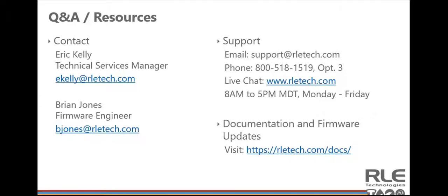That is correct. A lot of times what we'll find is the power will be somewhat variable. I see this less in data centers when the units are connected to a larger UPS that's doing power cleaning and whatnot. But that's essentially what's happening. The small UPS that your system is connected to is making sure any of the power fluctuation, brownouts, low voltages are not hitting the controller. And that can cause a little bit of jumping around in footage or some odd behavior from time to time when it's getting quote-unquote dirty power versus cleaned power. That's why you'll notice those odds and ends there.